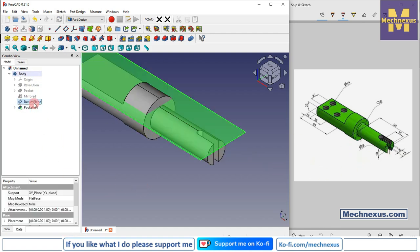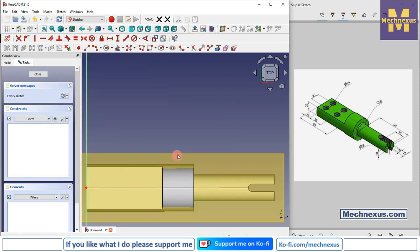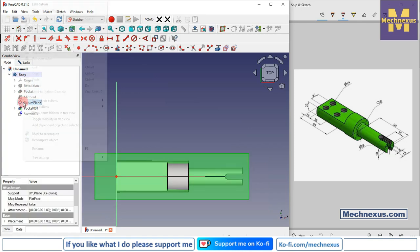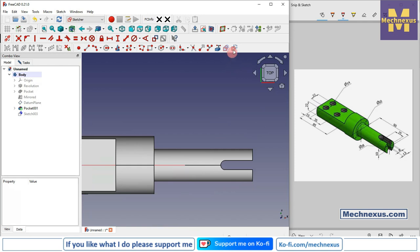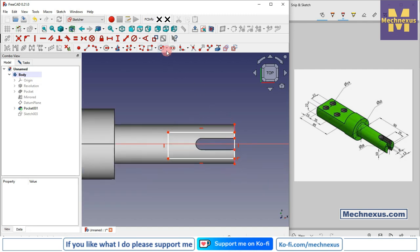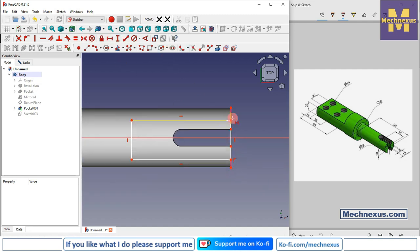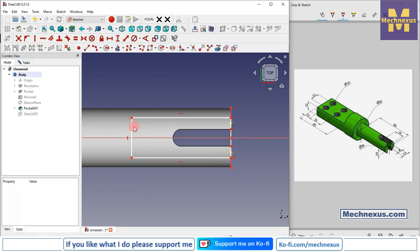Now we will again click on the datum plane and select this datum plane and click on the sketch, hide it, and now we will again click on the project geometry and project these two edges, and here I again create a rectangle, and again we will make this point symmetric. Select this point and this axis, and I will delete this line,